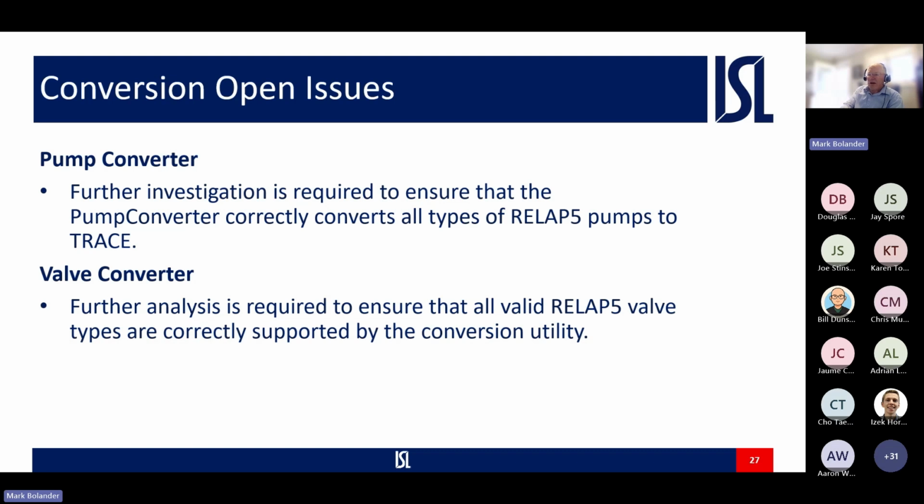With the valve converter, further analysis is required to ensure that all valid valve types are correctly supported by the conversion utility. So these are just areas that you need to be wary of and double check in your converted RELAP or in your converted TRACE model.